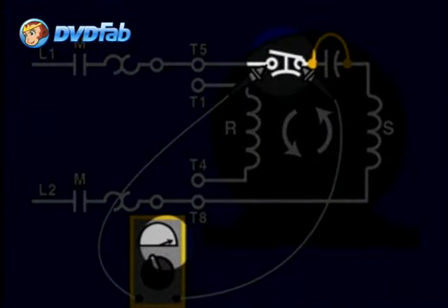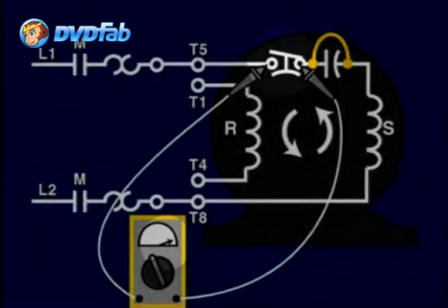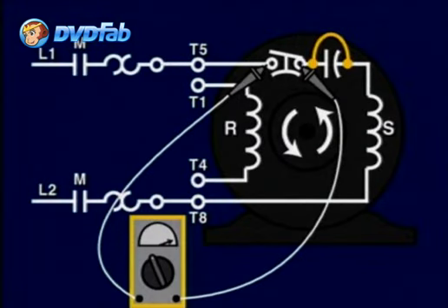If the switch is not good, you need to replace it and test the winding again to ensure proper rewiring and that the winding itself does not also have an open. If any of the windings are open, the motor would need to be replaced. If the windings are both good, the potential problem may lie on the shaft or on a binding load, thus not allowing the motor to start.